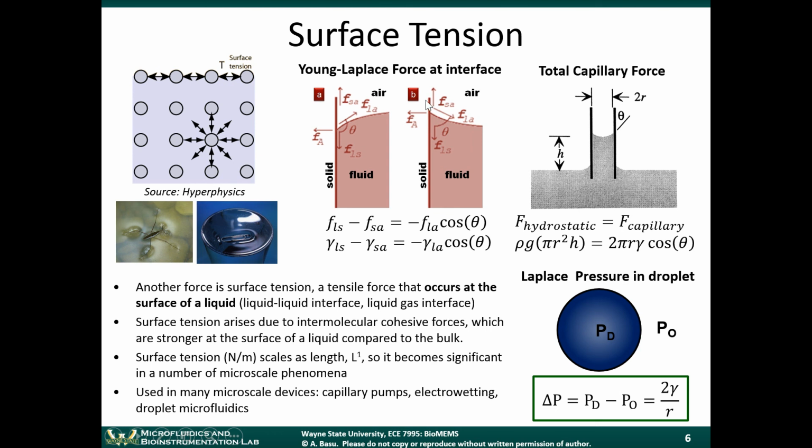By contrast, if the surface is hydrophobic, the water molecules will prefer not to be on the surface, so the water molecules will try to get away from there, creating more of a stack of water molecules here. We don't see these effects at the macro scale because the weight of the water is more significant than these surface interactions. I'll get more into that on the next slide. Okay, but at the microscale, if we were able to zoom in on this, we'd be able to see these.